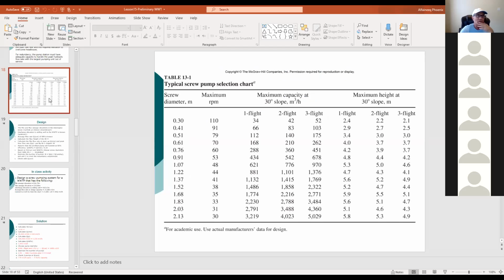So the head is 4.42. Yes. See here, this works. Everything around this area is okay. However, you need to judge with the capacity here. This is the maximum capacity given, all right? So we need to figure out what the capacity is here. We do that with respect to Q minimum. You need to satisfy Q minimum, and you need to satisfy Q peak as well, both of them.